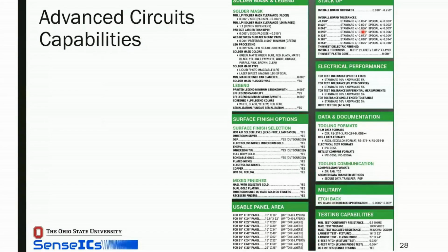So the question was, if you had one laser drill, do you then meet the, whatever minimum order to cover 1 million laser drills on the board? Okay. Again, it's kind of maybe, it really depends on the actual thing that you're doing. And yes, maybe 1 to 100 is good, but 1 to 1,000 is not good. You're going to have that conversation with the PCB manufacturer.